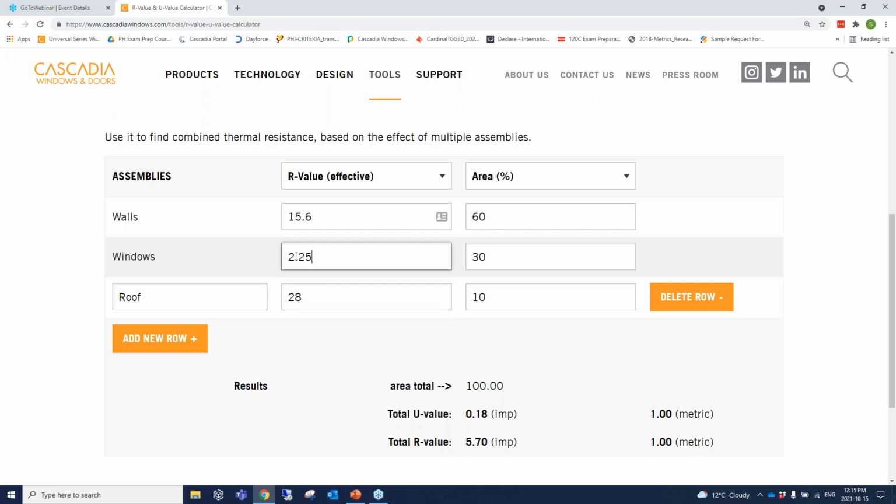If we take this aluminum window and simply swap out the aluminum for a low conductivity material like fiberglass, we're going to get about R4. Bam! Look at that. We're meeting our target. So that's great. Well, then what happens if we reach further? Let's go to triple glazing and see what that gets us. The R7.1 for a basic fiberglass triple glaze system. We have R12. So we're exceeding our target, saving a lot of energy.